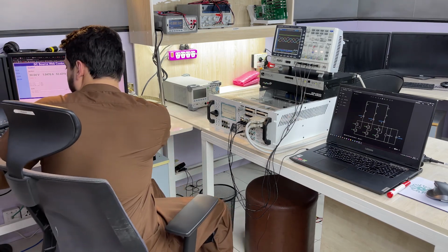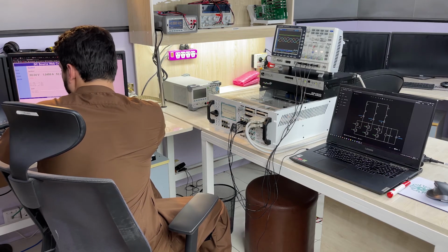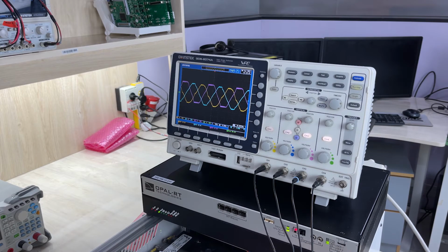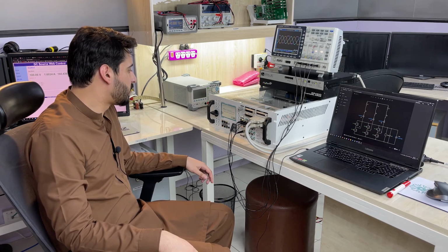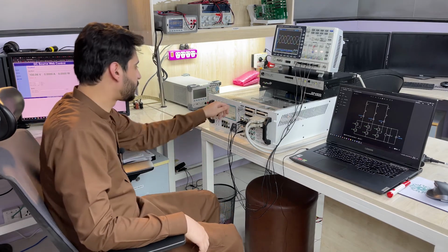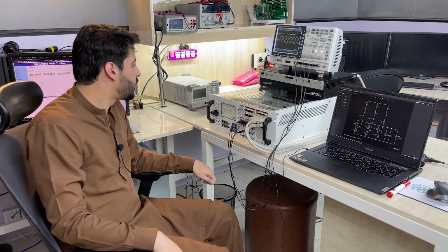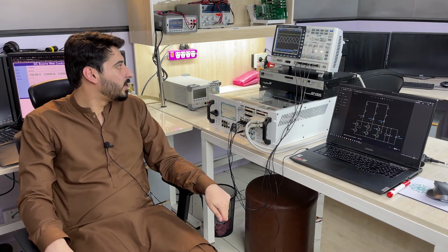To trigger an overcurrent condition, we will increase the DC link voltage to increase the current above the maximum allowable range of 10 amperes. As soon as we do that, you can see that the buzzer along with the fault status of overcurrent protection shows that the overcurrent protection is taking place right now. You can see that we've moved from the power mode to HIL mode again, and you can see that perfectly sinusoidal load current on the oscilloscope.